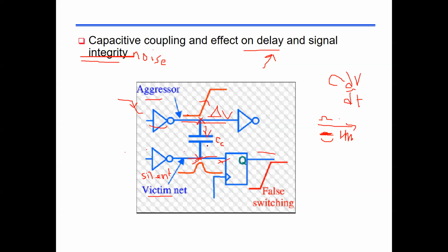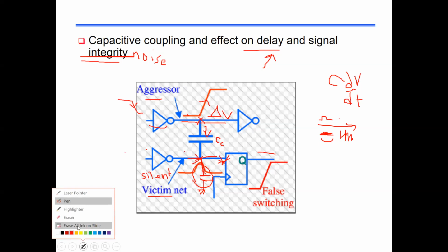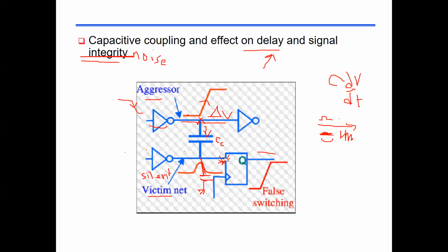And now this current, this transient current in this capacitor, is going to flow in the capacitance that exists in this wire, between this wire and the ground, because every wire has its own capacitance, whether silent or not. And the flow of this current is going to inject temporarily some charge onto this lower capacitor and will change the state of this node. This is the noise that we will see on this node here. Okay, and we will later tell you why we see noise if this is silent.